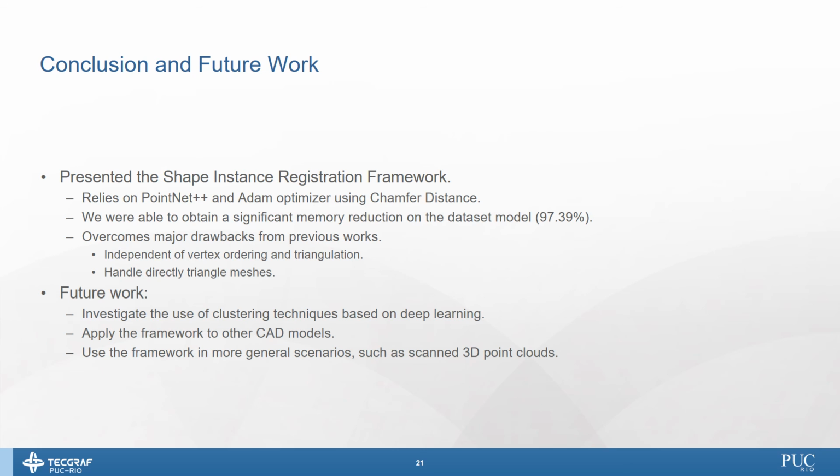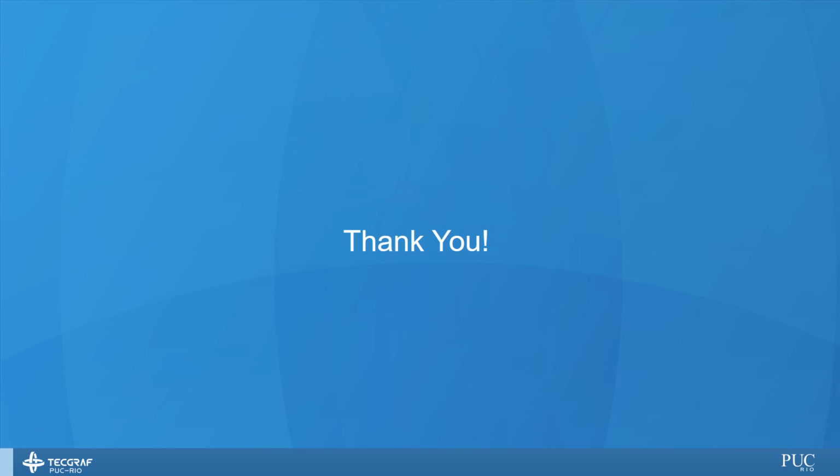We presented the shape instance registration framework, which obtains significant memory reductions on CAD models by relying on PointNet++ and Adam optimizing using the chamfer distance as cost function, and overcomes major drawbacks from previous works. As future work, we intend to investigate the use of clustering techniques to avoid the necessity of previous knowledge of the model, apply the framework to other CAD models, and use the framework in more general scenarios, such as scanning 3D point clouds. Thank you for watching.